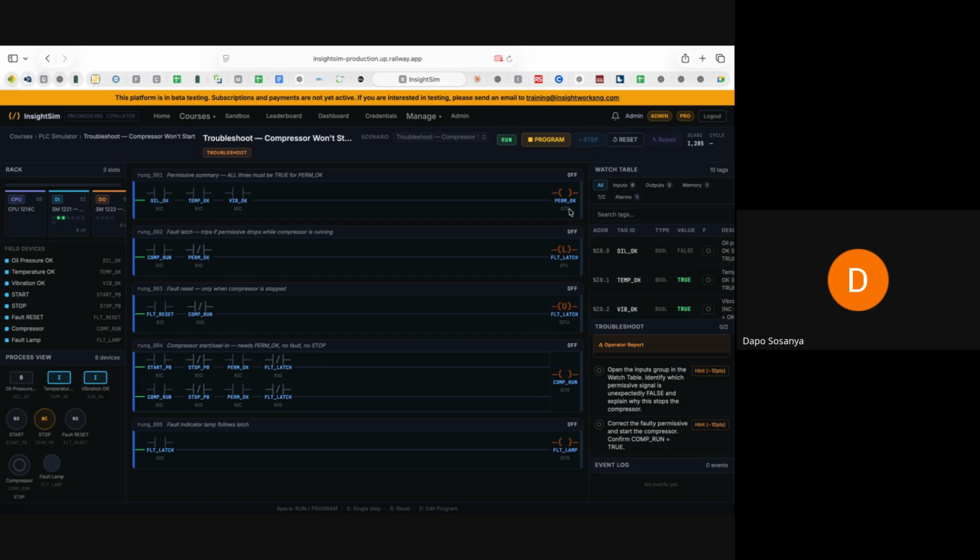So perm_OK is false. So that's why if you start the compressor on rung 4, you see that your start PB is on, your stop PB is on, but your perm_OK is the one breaking the link.